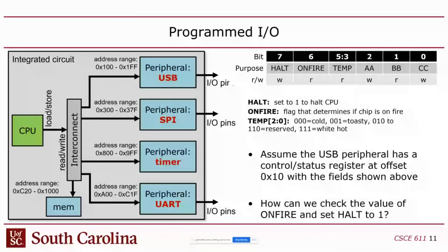This is because the Atmel 328P in the Arduino is an 8-bit processor that we used last spring. But I/O registers can be wider. They can be 32 bits, for instance. But this is an 8-bit register, and it's divided into 6 fields.